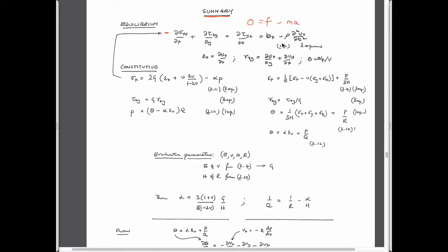is this, basically. This is the inertial term, this is the body force, and all these others are essentially body forces as well, depending on the sign convention. And so this conservation equation satisfies those. We have definitions of strains, both in normal mode and in shear mode, as displacement gradients. And we have an additional strain which represents the volume strain of the fluid. So the change in volume of the fluid over the total volume is the definition of this fluid strain.